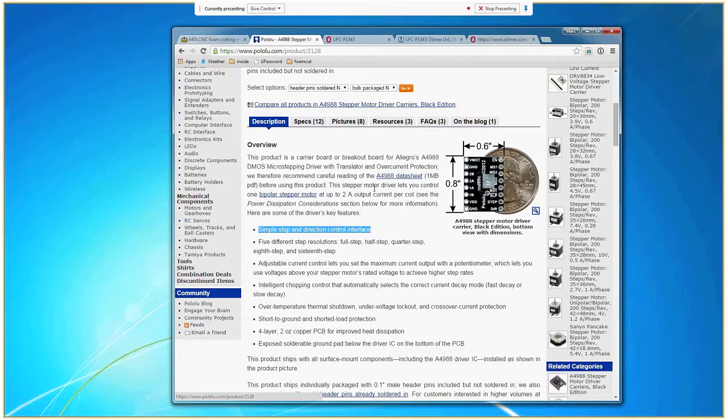So in order to connect a PC to that, in the past people have done things like use the parallel port, but of course there aren't really parallel ports on PCs anymore. The other thing is that Windows, Linux, Mac OS X, they're not real-time operating systems, which means you can specify a timer that runs really fast, but the operating system could take over for several hundred milliseconds and not run your timer and then come back and run it several times in a row faster than you thought. And the overall result is that you're going to get a poor foam cut.